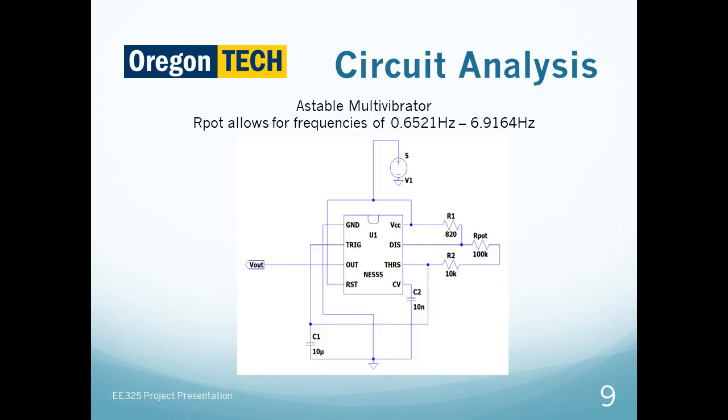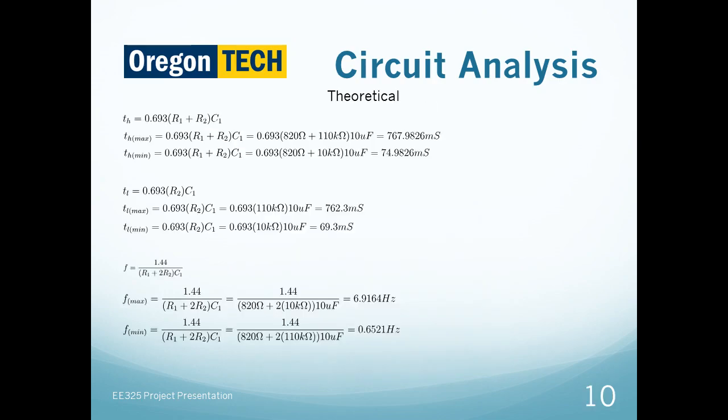The cornerstone of the time-varying control voltage begins with a 555 timer IC configured as an astable multivibrator oscillator. The 555 output frequency should be less than 20 Hz in order for the effect to be perceived as a rhythmic pulsing rather than a distinct, audible tone.